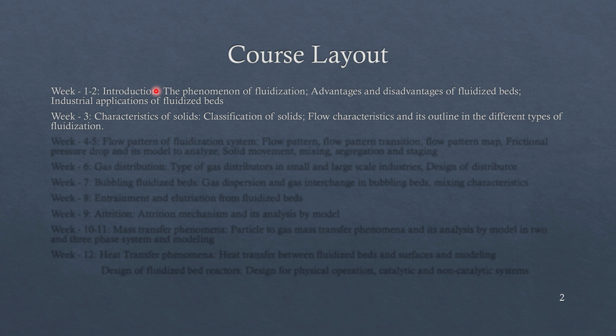The very fine particles, that is the smallest of particles, come under Geldart C. These particles would be cohesive in nature. Imagine them sticking together. It is very difficult to fluidize them because they rise together and move together because of their cohesiveness. Next, with a little increase in size, come the Geldart A particles.